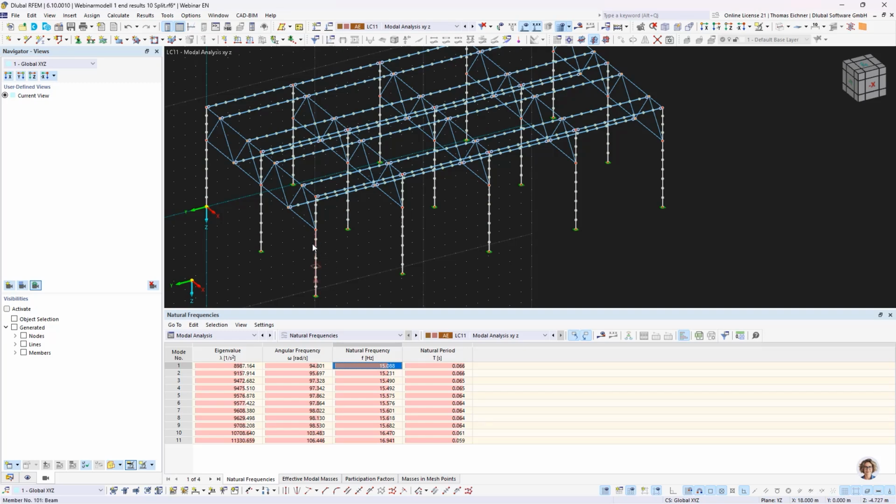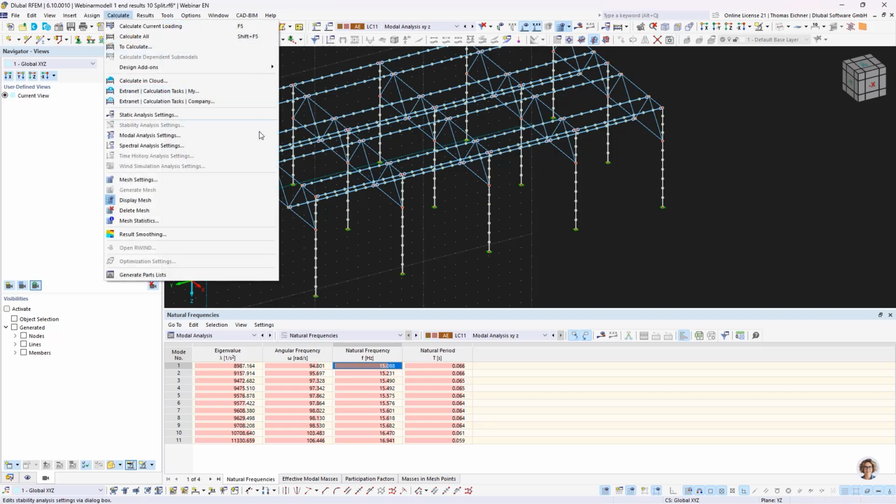With our mass matrix definition, this point could move in the x direction by 1, and that would be one mode. It could be moved in the y direction by 1. That's another mode. And it could rotate around the z-axis. That's the third mode. So for each of these points, we have theoretically 3 possible modes. And that means we can reduce our amount of modes if we reduce our amount of mesh nodes. And for those systems, we can just go for our calculation here.